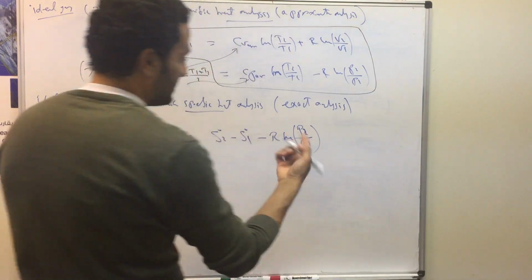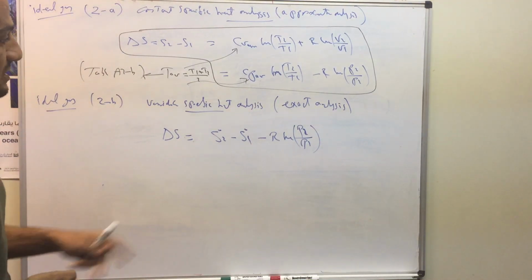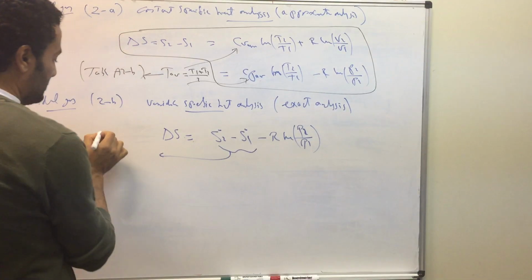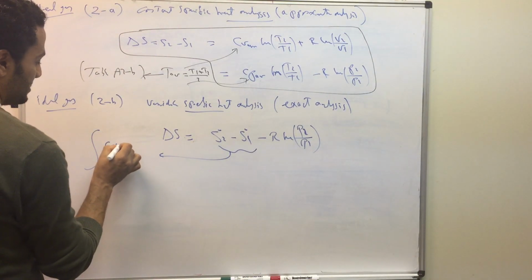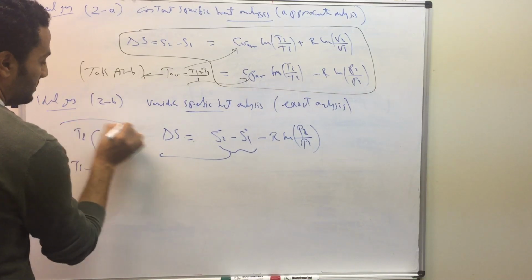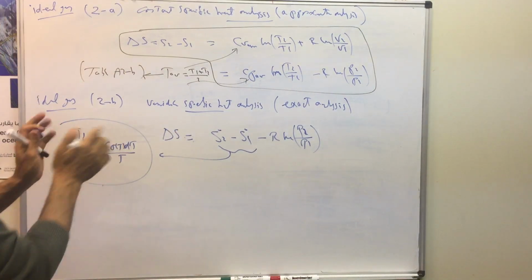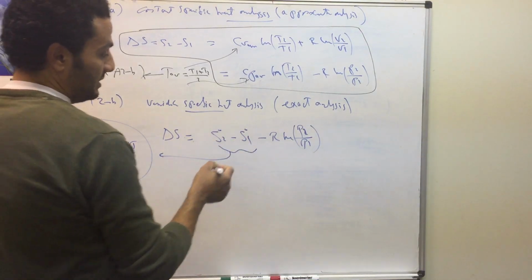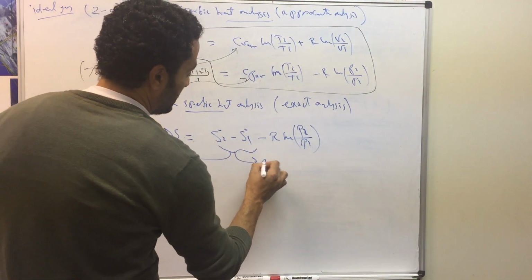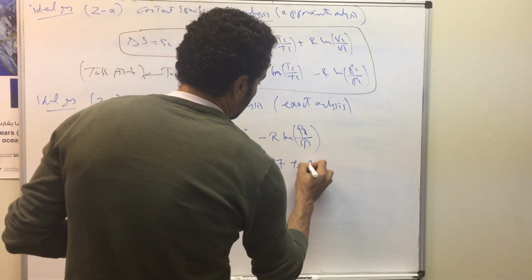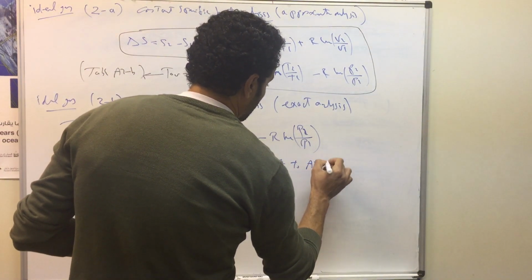So they considered the second T dS relation, and they did the integration, which refers to the integration of C_p as a function of temperature dT over T from T1 up to T2. They already have done this integration, and they reduced it to this value s naught 2 minus s naught 1, and those can be calculated from table A17 up to table A25.